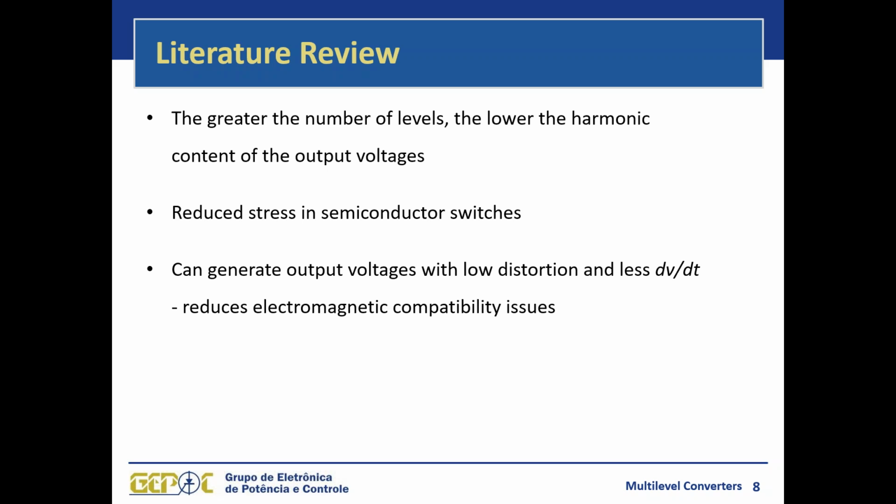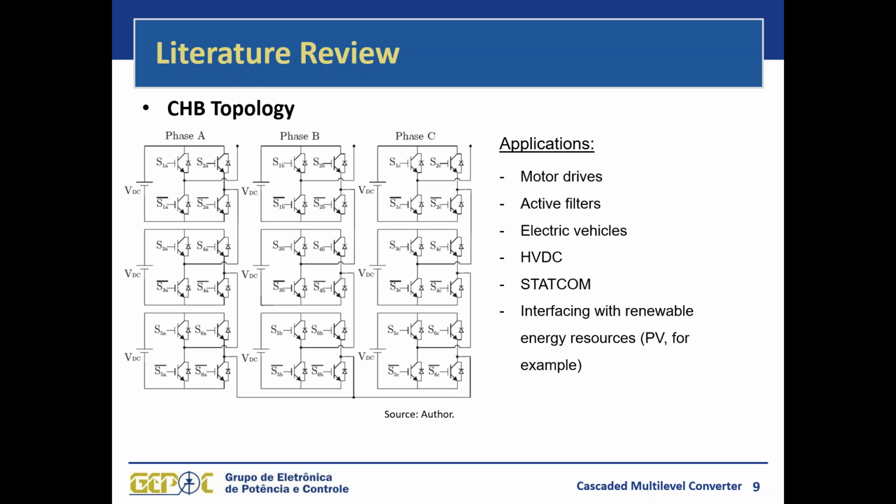In this context, one of the most widely used multi-level converters nowadays is the cascaded H-bridge topology that we can see here on these slides. Here we have an example of a 3-phase cascaded topology with 3 cells per phase.